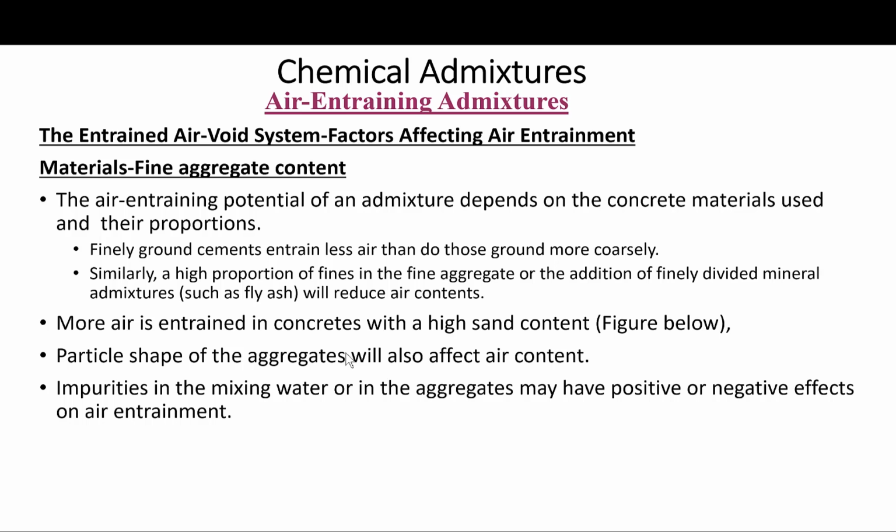The use of other admixtures, though, simultaneously with air entraining agents should be approached with caution, because they may affect air entraining abilities of the admixture. So when water reducing agents are used, the dosage of air-entraining agent frequently can be reduced while maintaining a given air content.